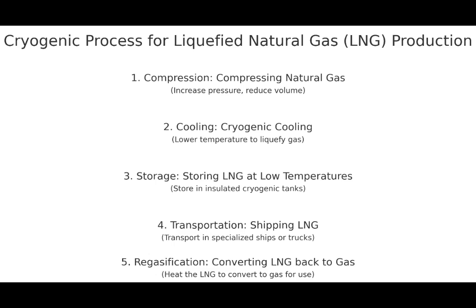As the temperature drops, the gas molecules lose kinetic energy, and attractive forces, such as van der Waals forces, dominate, causing the gas molecules to come together and form a liquid. The cooling step is designed to exploit the temperature-dependent nature of the intermolecular forces, which are incorporated into real gas equations like the van der Waals equation and virial equation.